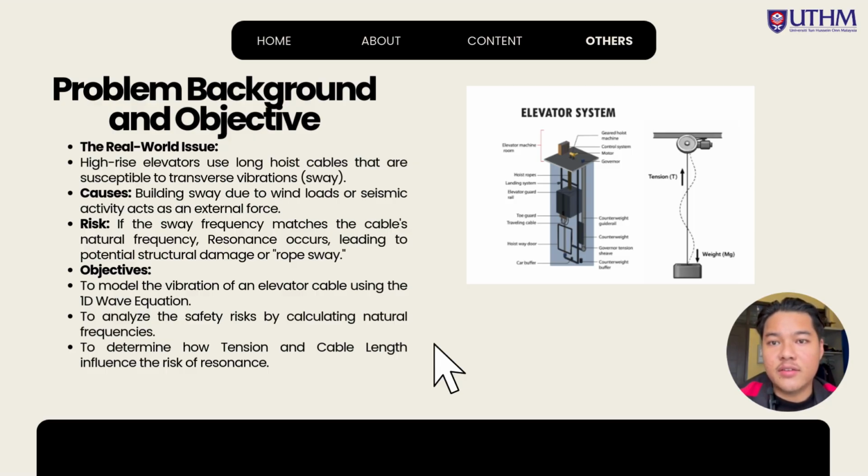The danger here is resonance. If the frequency of the building sway matches the natural frequency of the cable, the cable will swing violently. This can damage the elevator shaft, destroy equipment, and endanger passengers.